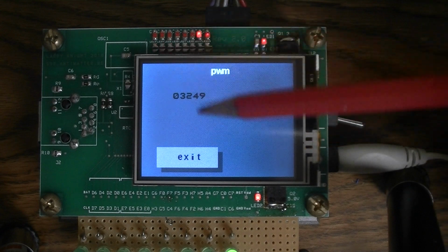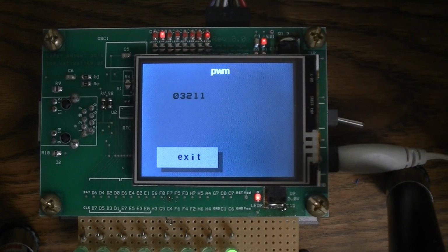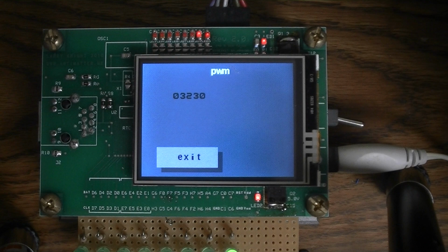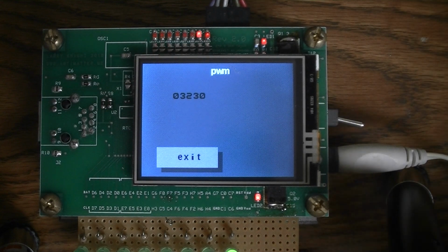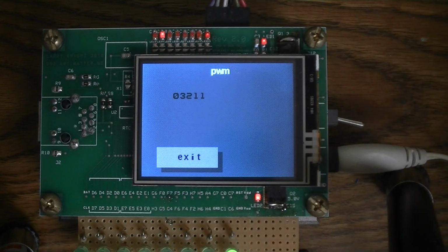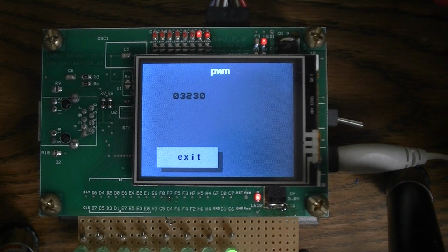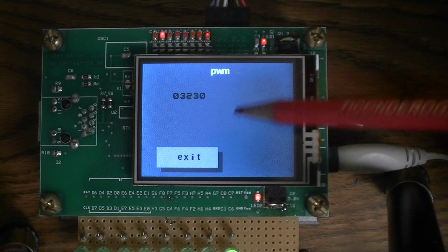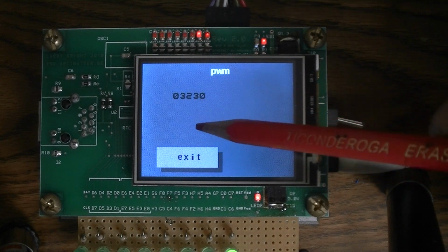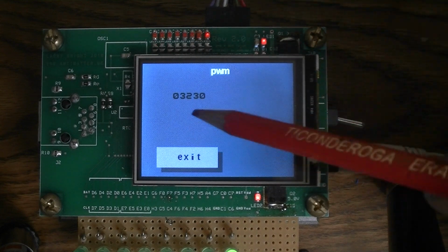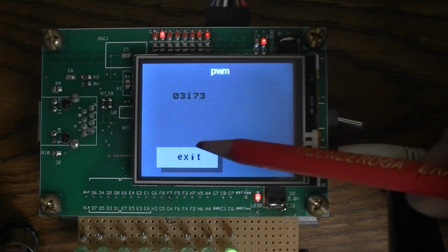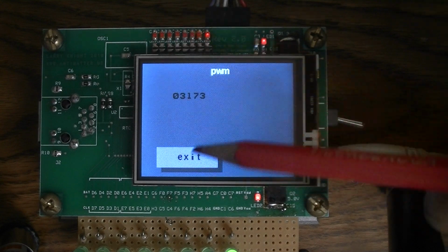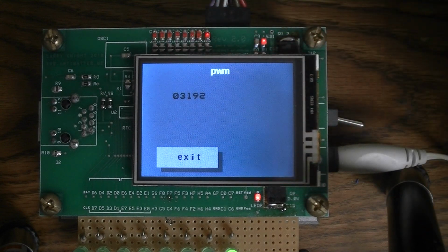The processor is sending out a PWM signal to the motor, and the motor is sending back the Tach pulse that I showed on my last video. And timer 0 in the processor counts every time there's a pulse from the motor Tach, and so it continually counts upward.